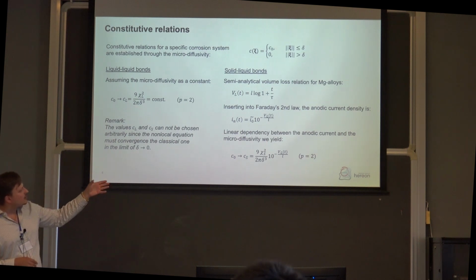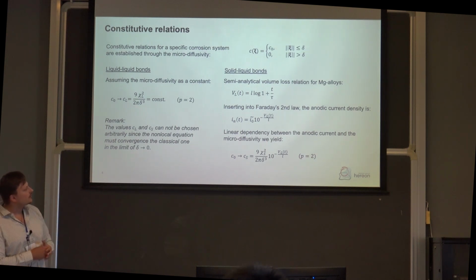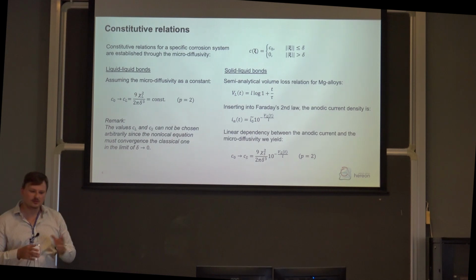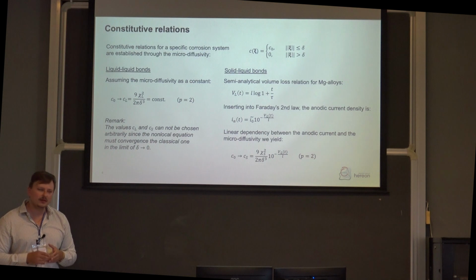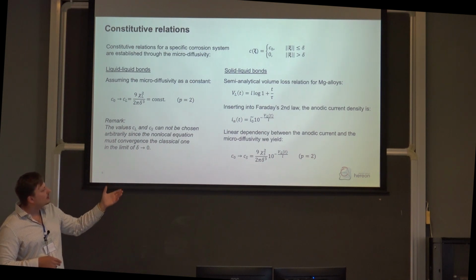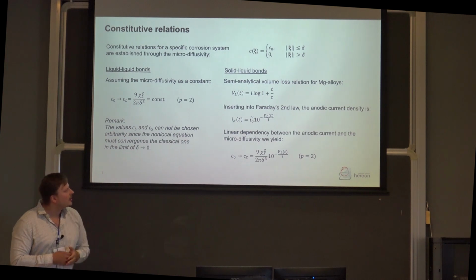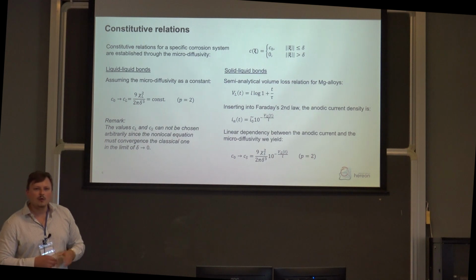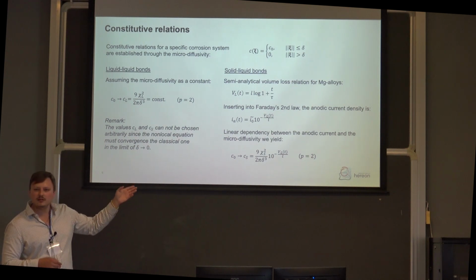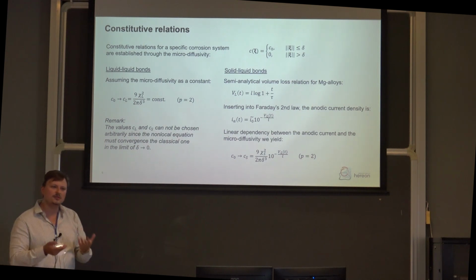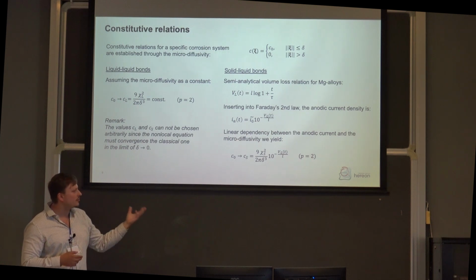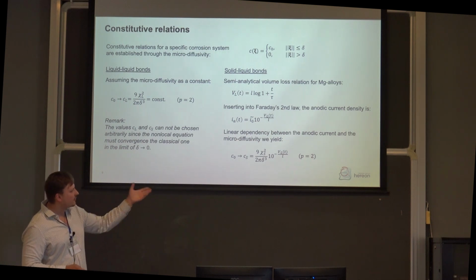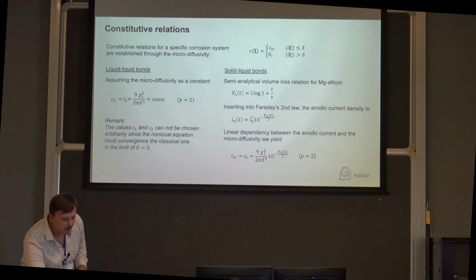In the solid-to-liquid bonds, we make, for our problems, the assumption that we define a semi-analytical volume loss. So this is something that can be related to experimental data. And based on this semi-analytical relation, by means of the second Faraday's law, we can calculate the current. And thus, what we end up with is a diffusivity which is implicitly time-dependent, specifically on the volume loss of the sample. So this is a constitutive relation. There are different ones that we can use, different ones in the literature. But we found that for our problems, this has been working very well.